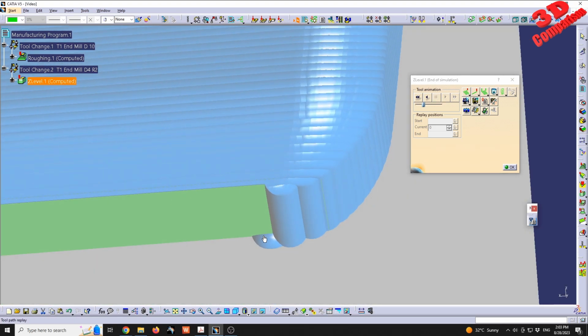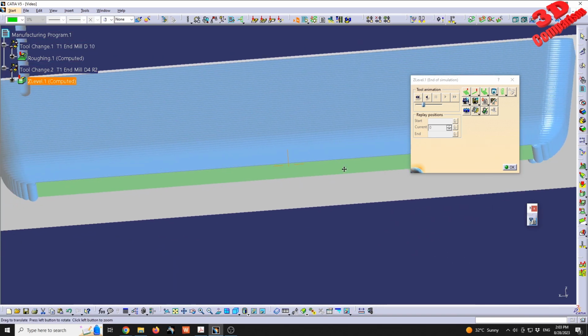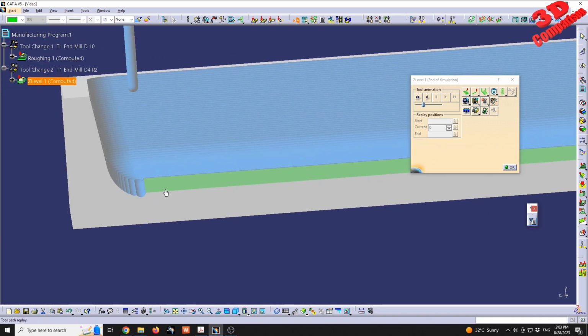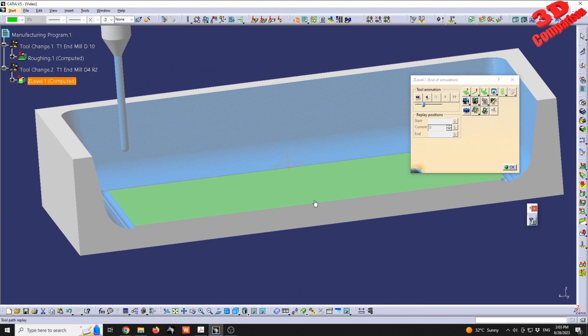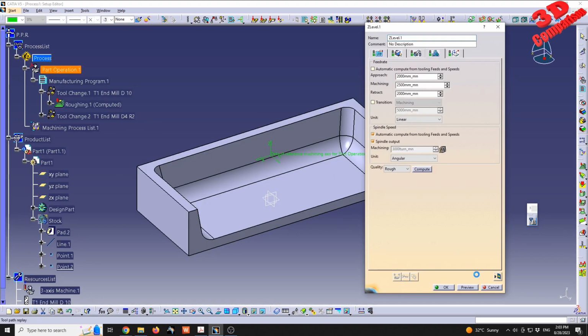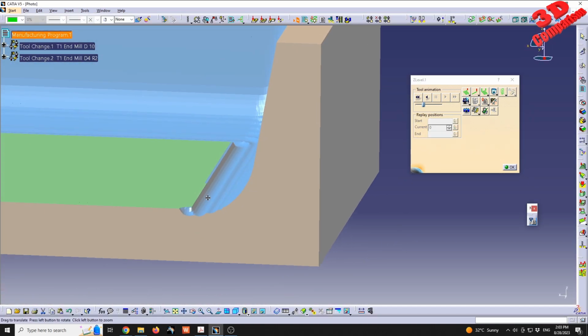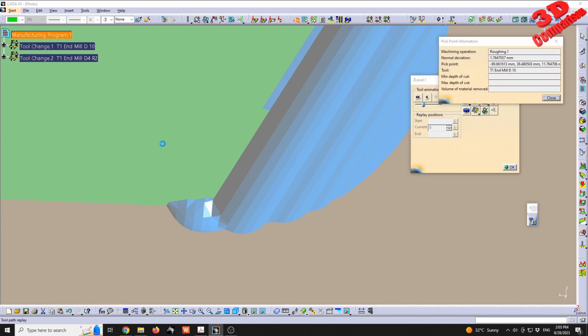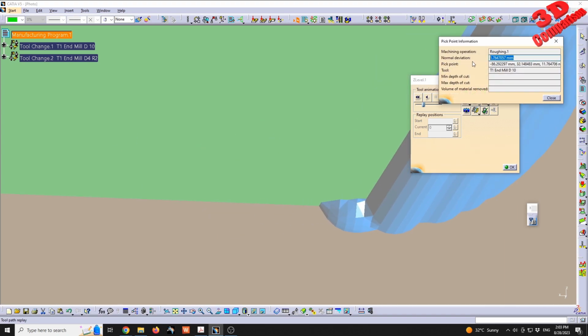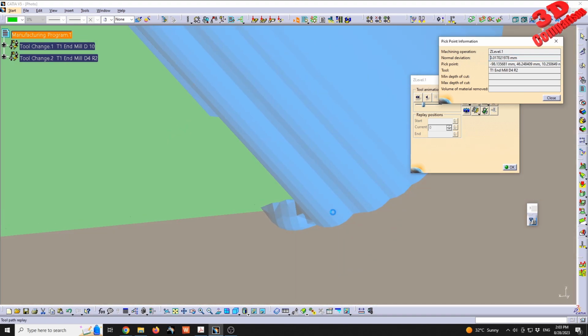So we're going to see that over here we're going to have those areas. We can also add the bottom face within the same ZLevel, or come with an additional operation at the end. So if I click OK and go back again, go on the camera, we're going to see that after this operation we're still going to have the nominal value. So we see now we have the nominal deviation 1.7 over here on all the bottom area, but we have some regions where we'll be closer.